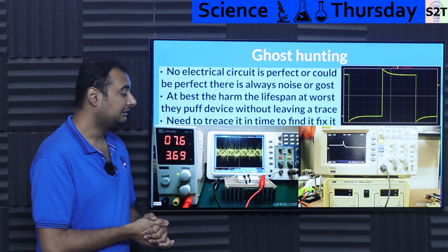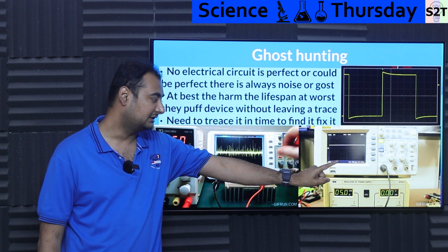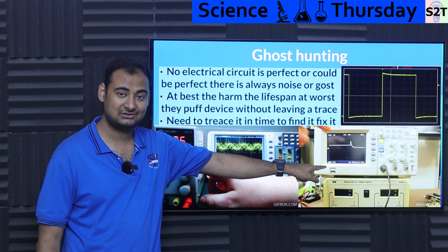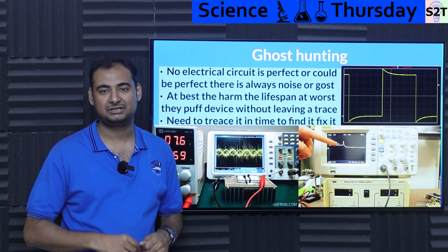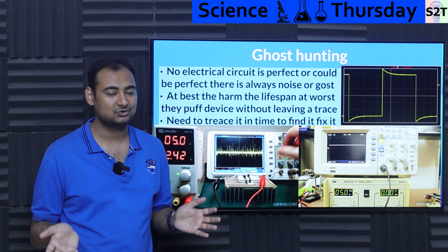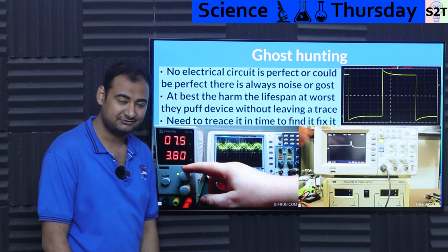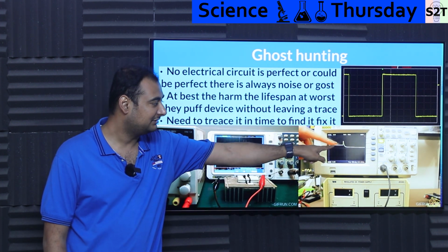For example, this individual went dumpster diving and found a regulated DC power supply, a linear power supply. Very happy, and he did it. Now he had an oscilloscope, so he connected it. You connect something, load it up, measure with a multimeter, that's what most people can do. But if you connect an oscilloscope, you can see things. What kind of things? This power supply has a surge shock, meaning you turn it off, it gives a spike.